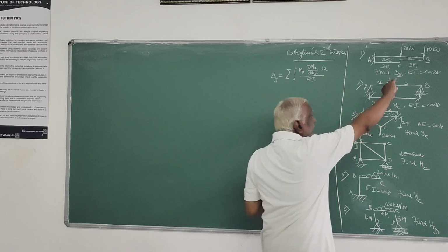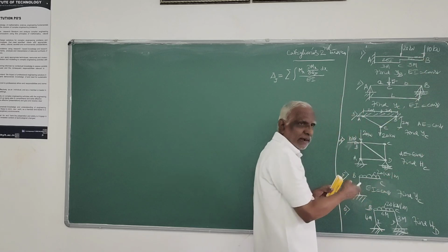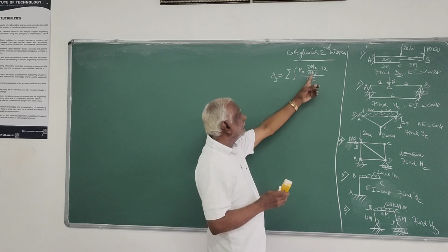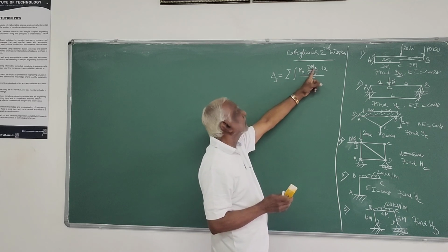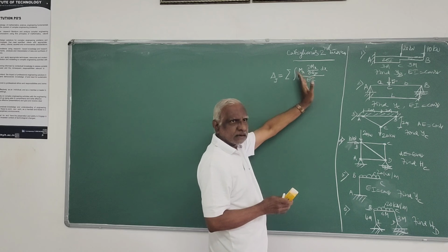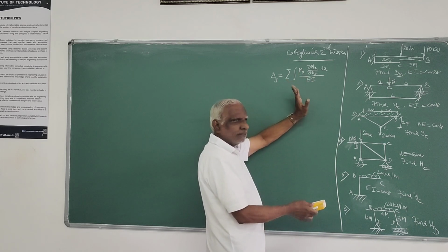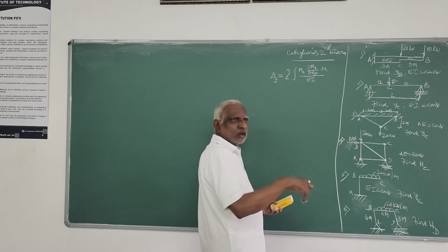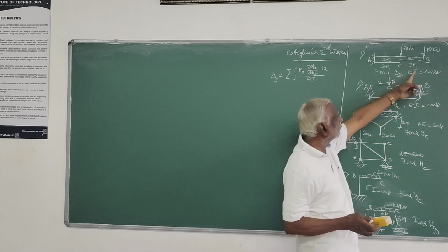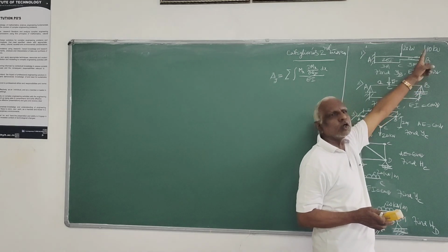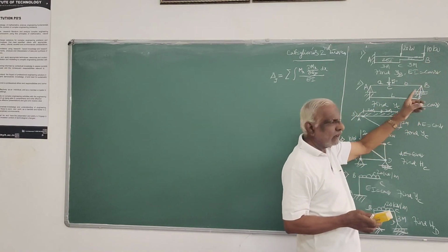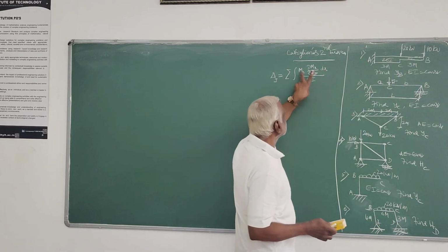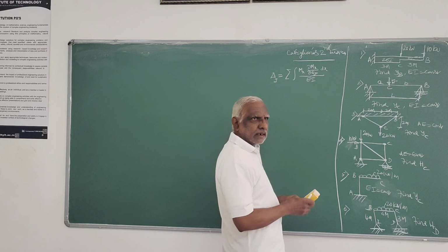So if you want to find slope, then you have to apply a moment as the load. Q is the moment applied. You have to apply a moment and find the moment at various sections due to that moment also, which is the fictitious moment. Ultimately you can put that moment value as 0. Here they ask you to find slope at P, you apply Q moment and take the moment at various sections, get M_x and partial M_x by partial Q.